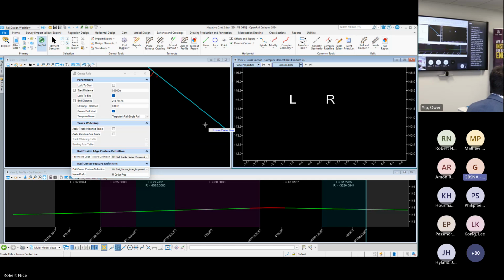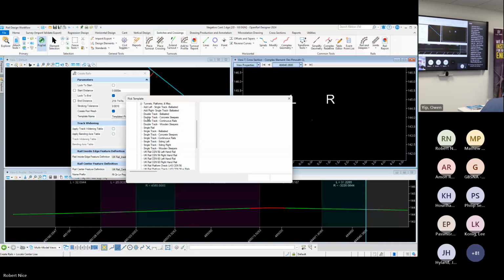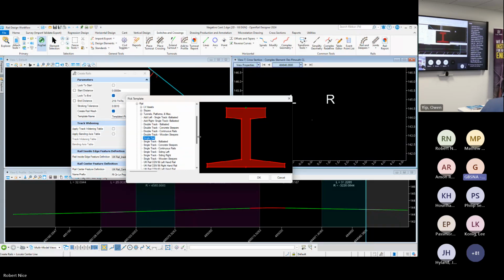And then we're going to link to another template, which is going to give our rail plane, our track plane. Again, just another check. This command is quite easy. It does need a template library. If you've never seen a template library before, if we click on this button here, it's basically a bunch of sections which we push along our geometry to create the mesh model.